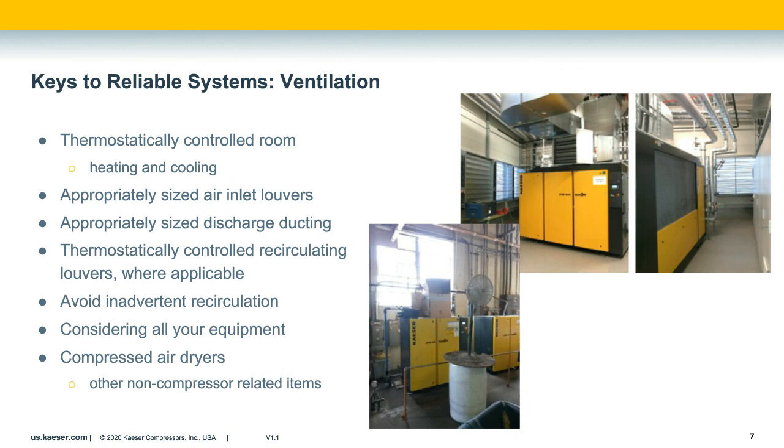Likewise, how we dispose of the waste heat from the compressor will also affect performance. What we see in the picture here at the bottom left is a compressor with a makeshift duct. Not recommended, especially something that's flammable. This is actually cardboard. However, the customer was trying to figure out why their compressor on the left was overheating constantly, but the compressor on the right was totally fine. So the suggestion was, hey, start pushing the air from the discharge away from the machine, and let's see if the compressor was actually inadvertently sucking in hot air, which it actually was.